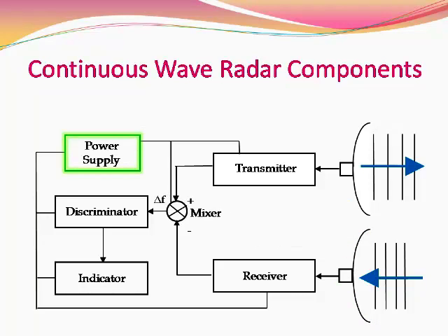And all these blocks are having the power requirement. So a power supply is separately shown in the next block diagram, and the RF oscillator we are going to use will be a simple sine wave generator of hundreds of megahertz or even gigahertz. So at hundreds of megahertz, we may consider a low power oscillator with a high power amplifier, or a direct high power oscillator like a magnetron or similar vacuum tube devices.